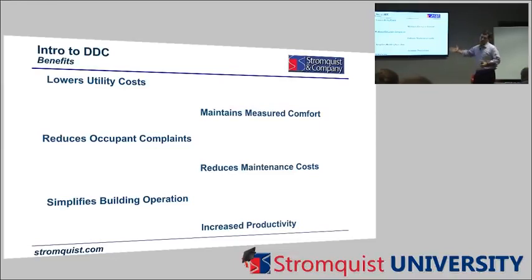It reduces maintenance costs. If I go in and program a lead-lag scenario where I have two pumps and I want to alternate the runtime on each pump, give this pump a break for a little while and then let this one go and then swap, obviously I'm going to reduce the maintenance cost because I don't have both of them coming on all the time, or none of them working, that kind of thing.